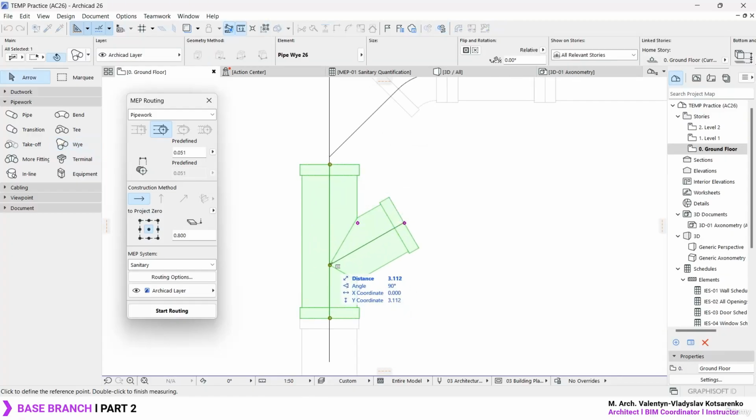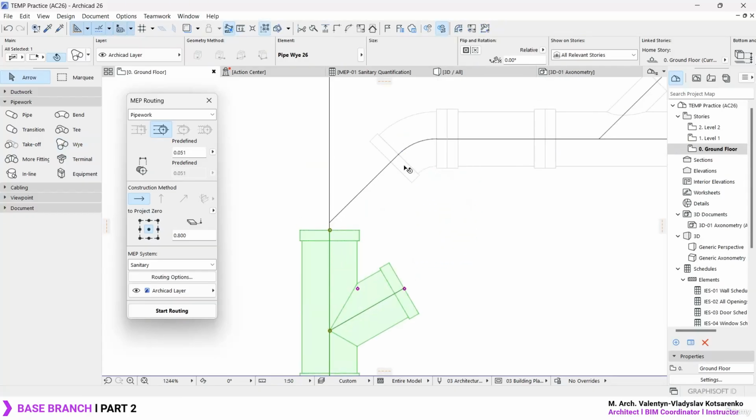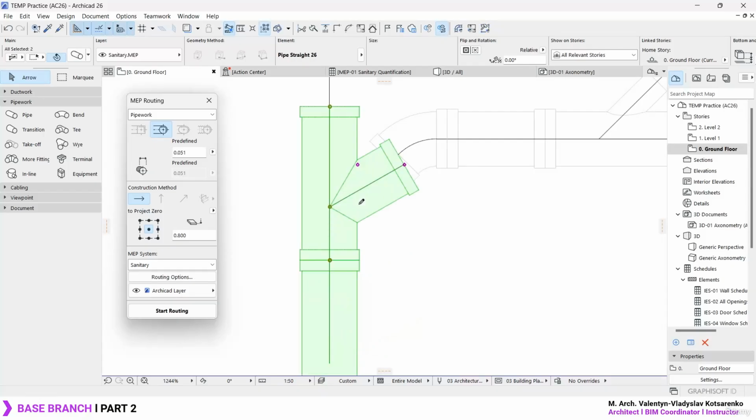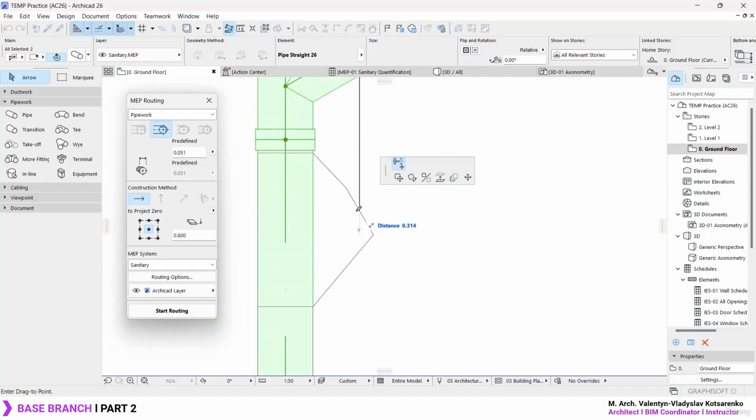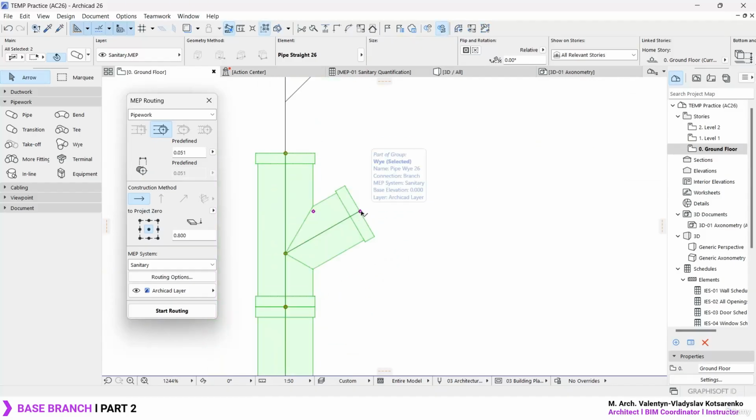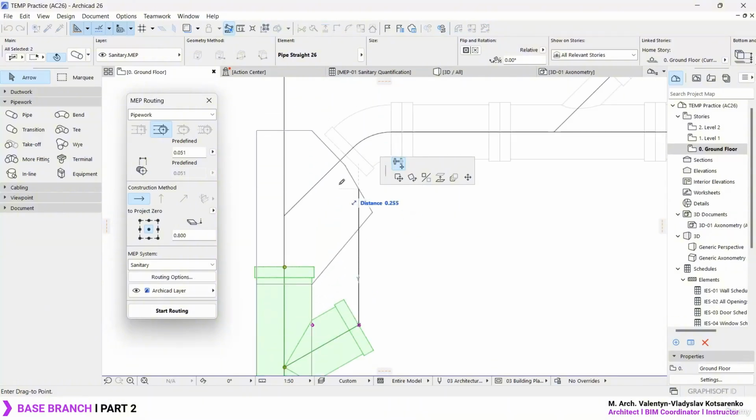Now we need to connect this branch, displace it somewhere around 0.232. So let's select this node, activate the moving line, 0.232. Okay, usually I just don't move this directly because I don't really like the position for this node. It's really terrible, but another easier way to move in line is you can simply select this node over here, which is going to be much easier for this case.